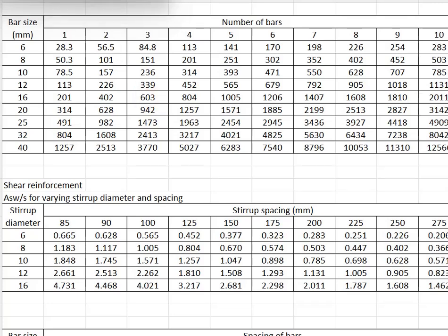If you have an issue with the spacing, you may increase the bar size while providing 2 units of reinforcement. The provided bar area will be slightly larger than what is required. Under most circumstances, it is applicable, except for the case of 10 mm to 12 mm diameter reinforcement bar.